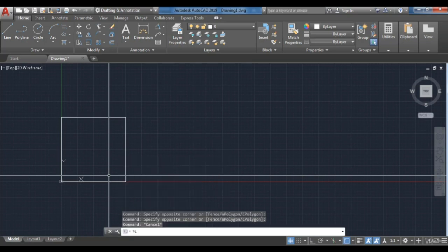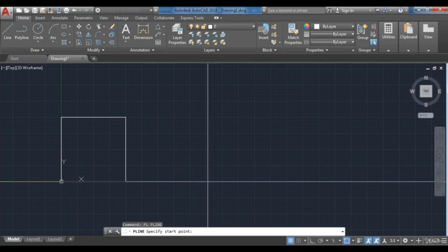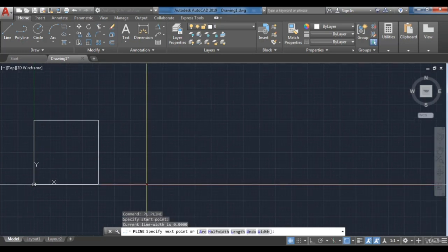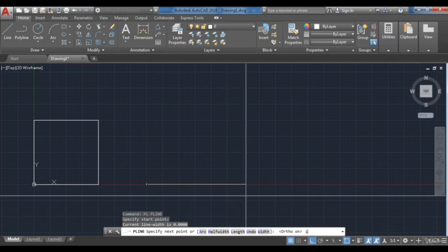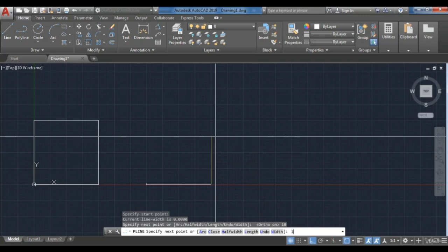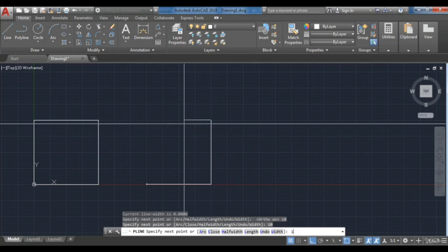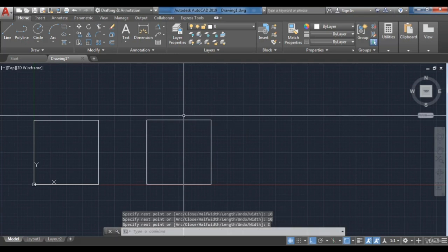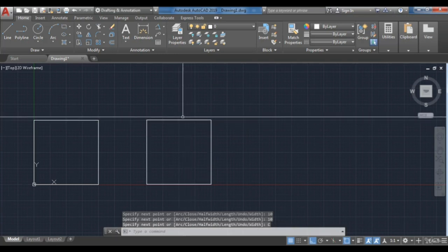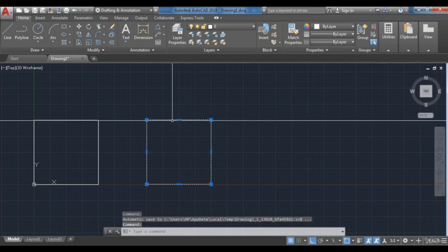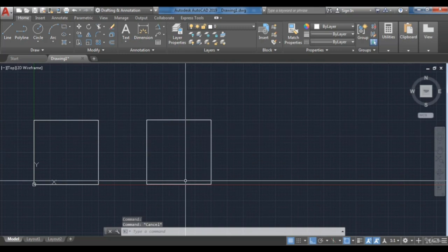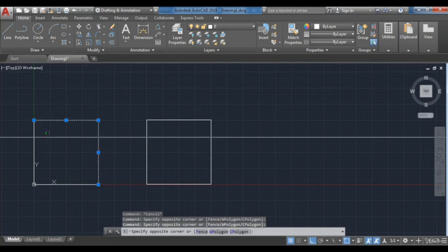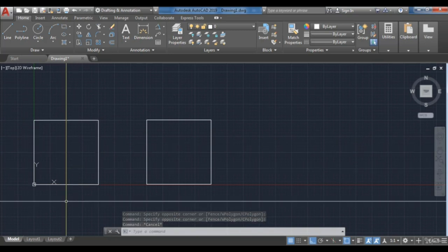But if you take polyline and draw, for example, a square 10 by 10, specify the first point, take ortho mode, I'll take 10, 10 above, 10 to the left, then close, C, enter. Now if I choose any point on this shape, you can see that it selects the whole shape. So these lines act as one unit, and the lines drawn by the command line, each one is separated from the others. This is the main objective of this command.